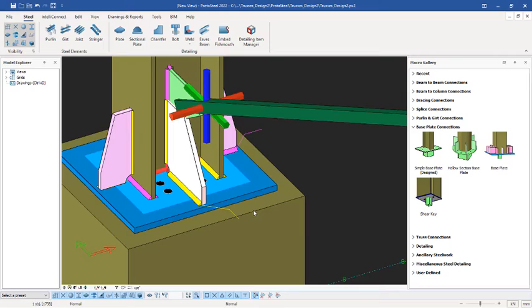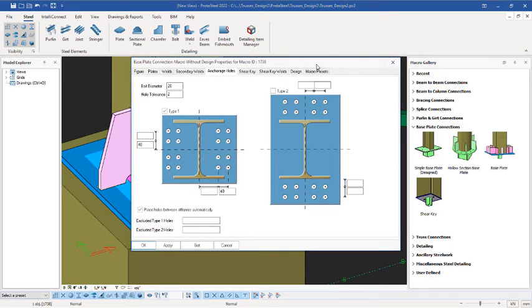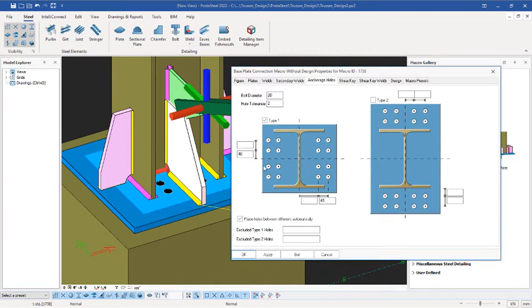So I will press the enter key on the keyboard because I still have the micro selected. Right, so the dialog will come up just like this. Once you have this dialog, I will remove this 40 I'm having here, and then first have 40 behind here, since I wanted only 2 holes at first and not 4. So I click on apply now. You can see I'm now having only 1, and the distance from the web to where the hole is located is just 40.